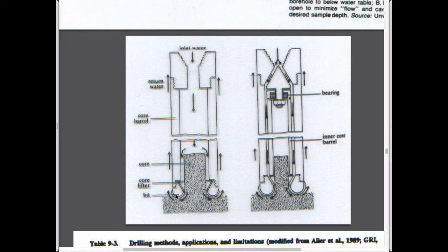So you have a long tube, in 5-foot sections, 10-foot sections, 20-foot sections, whatever they are, and the tube is hollow. At the tip of the tube it has a cutting shoe, which is studded with diamonds, which are these portions here. It's a torus, obviously, it's like a donut. And you just rotate it, and it slowly abrades this material. It doesn't chip it off, it abrades it, and slowly works its way down further and further.